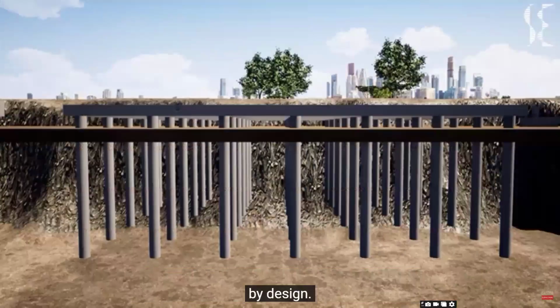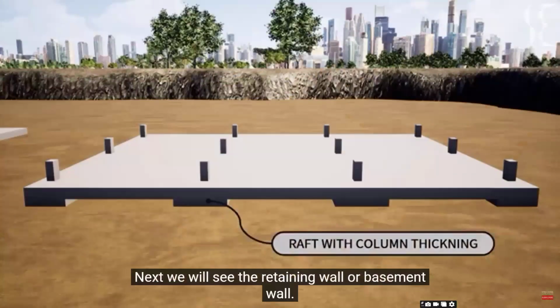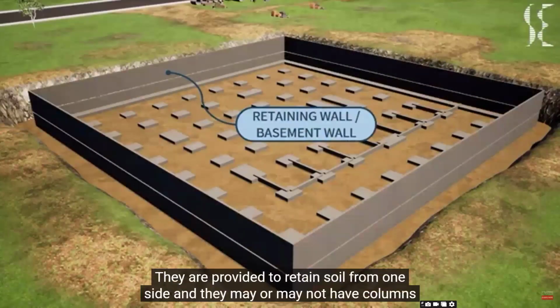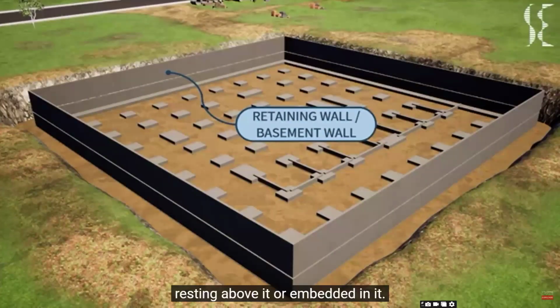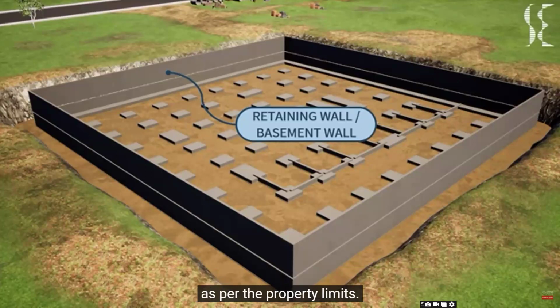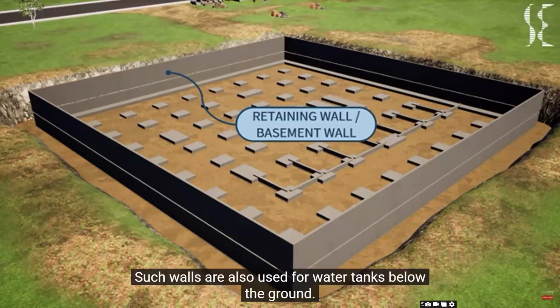Next we will see the retaining wall or basement wall. They are provided to retain soil from one side and they may or may not have columns resting above it or embedded in it. Retaining wall or basement wall may have strip footing which may or may not be eccentric as per the property limits. Such walls are also used for water tanks below the ground.